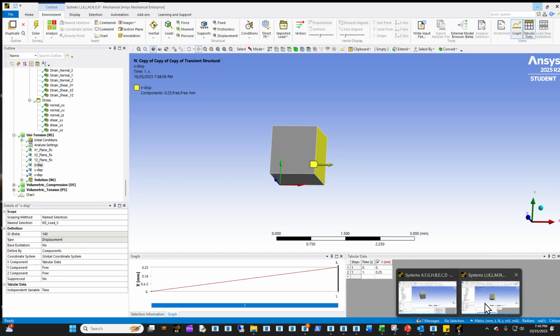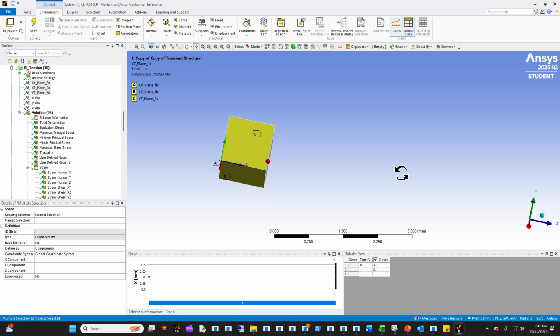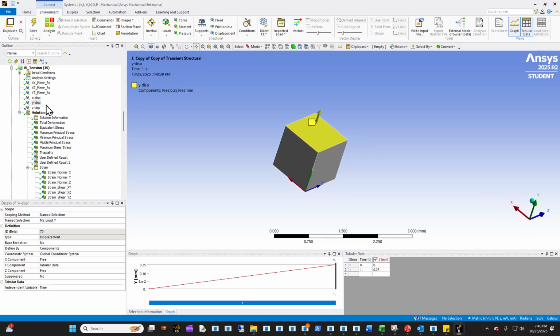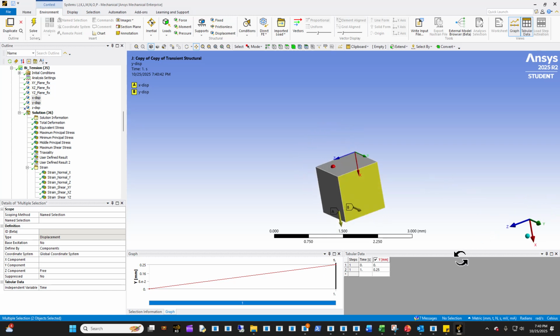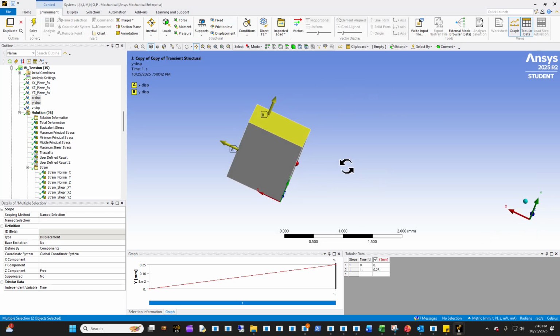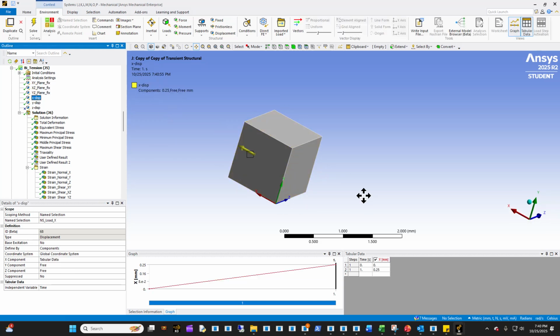So let's look at it in the actual example, right? This is uniaxial tension, uniaxial compression. Let's look at biaxial tension. It's right here. What you have here is still that these three surfaces are constrained along the origin, and you have a face moving that way, and a face moving that way, right? You can see these two faces move out this way. Maybe this is a better way to look at it. Let me rotate it a little bit. Okay, so this right here, that right there, and then you have these three planes fixed in place, and that gives you the tension in two different directions.